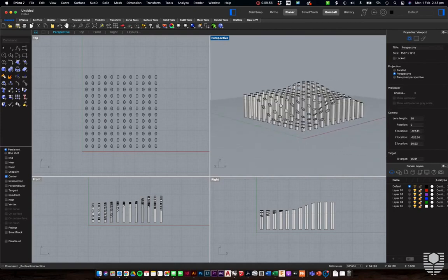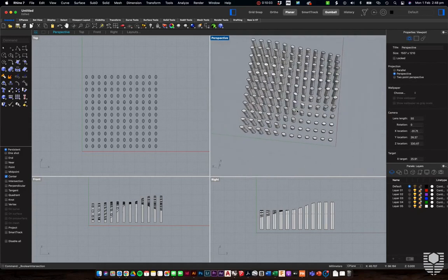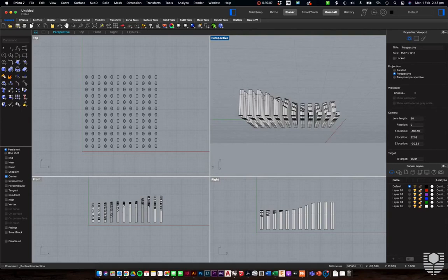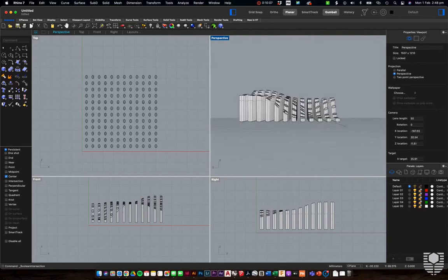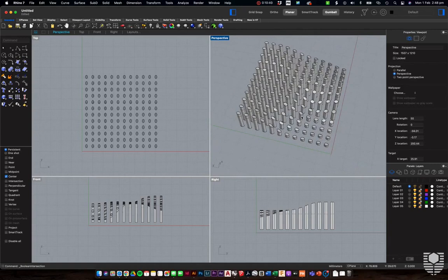Now, yes, we could extrude to individual heights, but getting these faces to talk to each other so perfectly would be very, very difficult to do manually. So again, we can create something pretty powerful. We could then go and add another layer underneath this and then boolean those together so that we just have these elements sticking out of a tile, and then maybe that's a tile that we create for our assessment. But you can see how intersection works there.